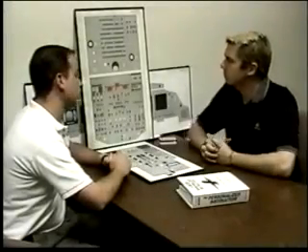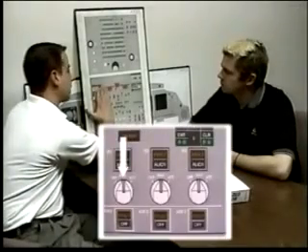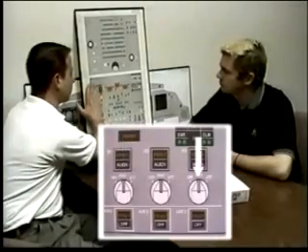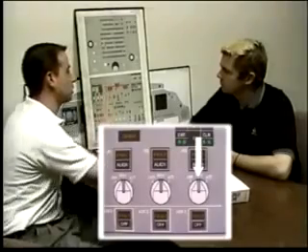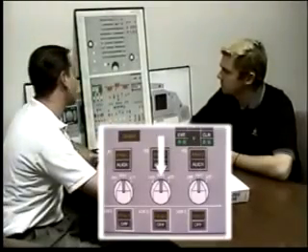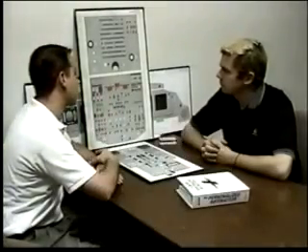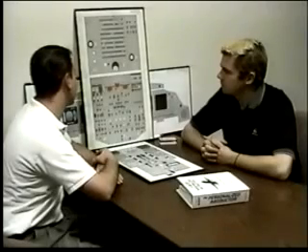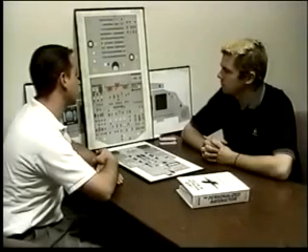Break this down into simple terms, and the way I remember it is ADIRU number 1 is for the captain, ADIRU number 2 for the first officer, and 3's in the middle as a standby. Remembering that all 3 IRs provide a mixed IRS position input to the flight management guidance system.